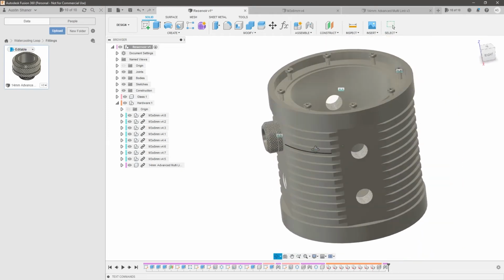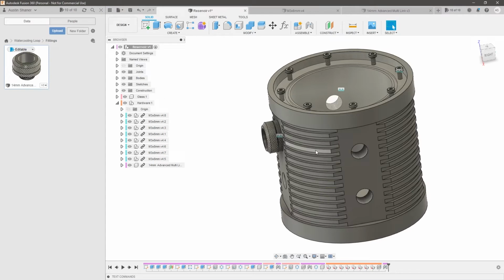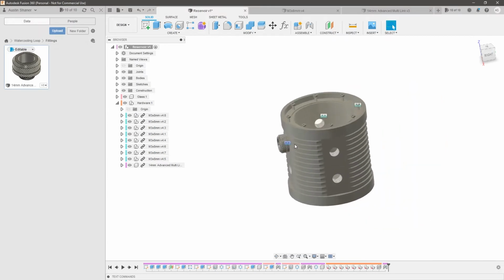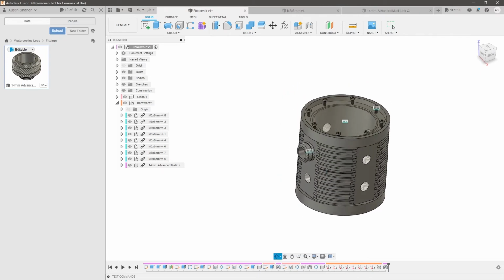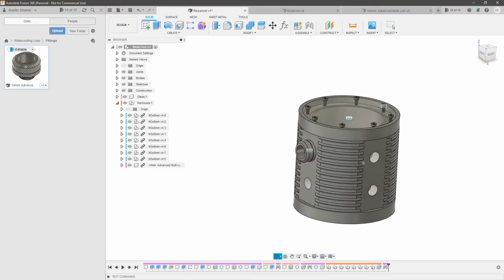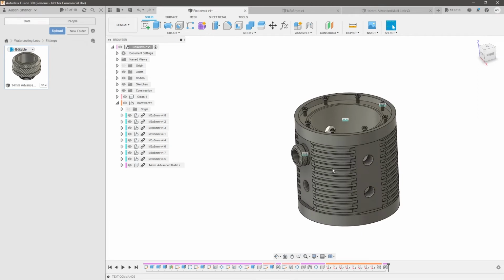We could either bring this into our computer file and then start creating the pipes from there, or we could create the pipes in here and bring all of that into the computer file. And in this case, because I need to reference geometry that is on the radiators and the graphics card, etc., I would actually choose to probably just get the fittings that I know I want to use in place in this subassembly, and then bring that subassembly into the computer file and draw my pipes from there.